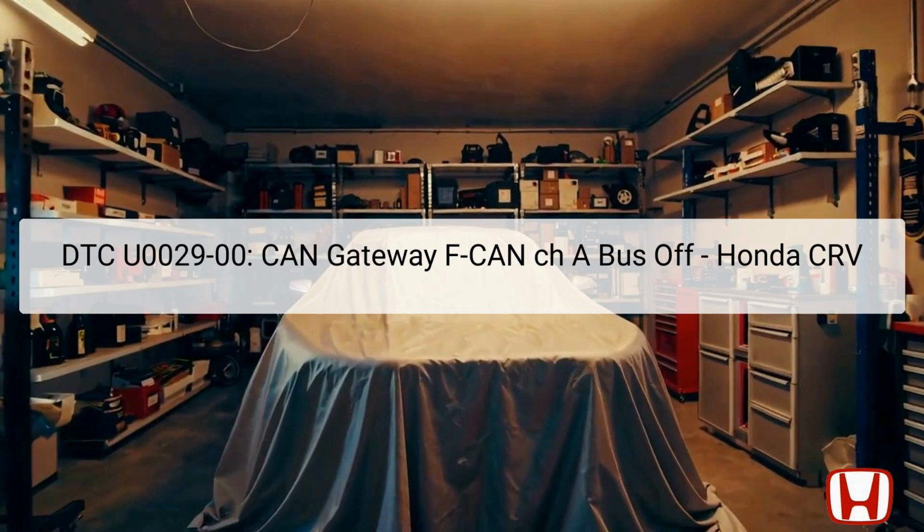The CAN system allows different electronic control units, ECUs, to communicate with each other without much wiring. The CAN gateway is connected to several modules through a series of connectors. In terms of location, the CAN gateway is typically found near the fuse box or behind the dashboard. When this error occurs, the vehicle may exhibit symptoms, including lack of communication between modules, leading to performance issues or warning lights on the dashboard.